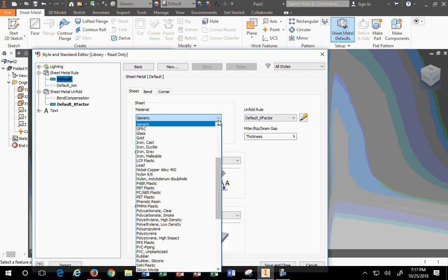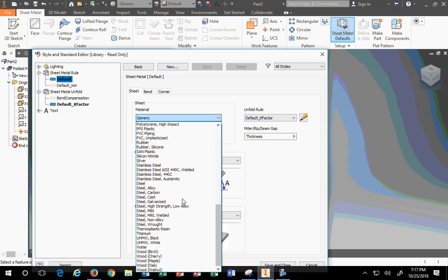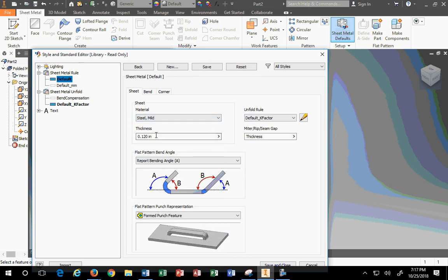Now annoyingly, let's go back to steel, mild steel. The thickness, it doesn't give us the information by gauge. Do you know that? You see that? Why? Because it varies. We proved that point already. That's why the first thing I did was jump online and say, well, what is 16 gauge? Let's go find out. Well, 16 gauge, depending on the site you go to, is a different number. And depending on the material, it's a different number. And we always have to appreciate the reality is that it's nominal.